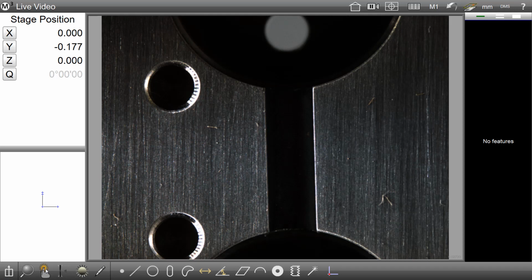You will see that the video probe displayed in the toolbar is highlighted in an orange color to indicate that a teach is in place. To remove a set teach, use the Unteach button in the bottom of the toolbar that will be displayed when any teach is in place. You will see that after pressing the Unteach button, the tools are displayed back in their standard monochrome fashion.